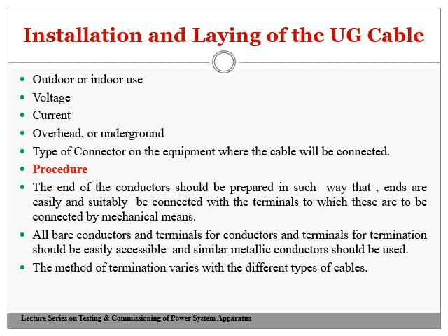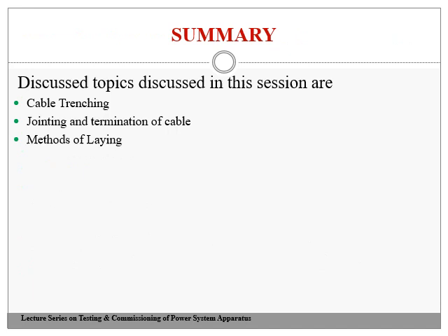Now we'll see the procedure. The end of the conductor should be prepared in such a way that the ends are easily connected with the terminals, to which these are to be connected by a mechanical means. All bare conductors and terminals for termination should be easily accessible and similar metallic conductor should be used. The method of termination varies with the different types of the cable.